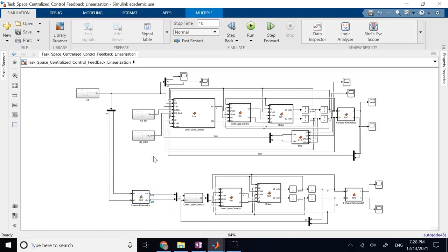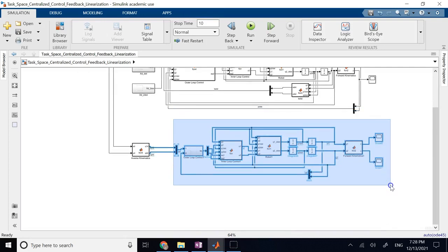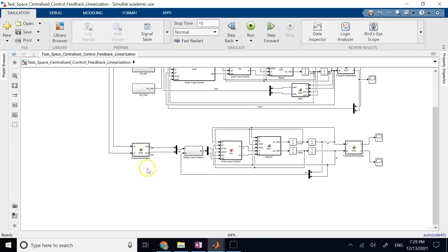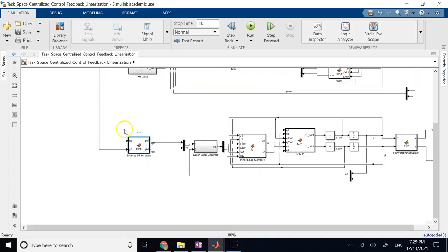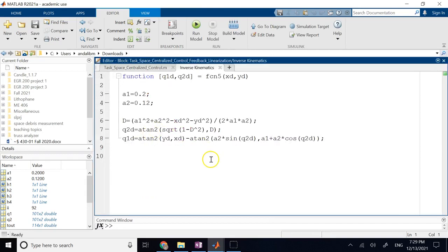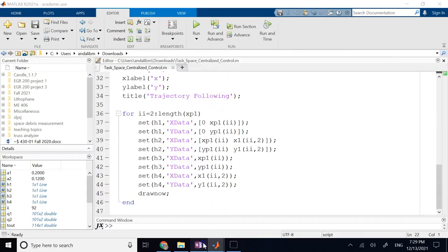Okay? As long as your inverse calculation is always possible analytically, it might not be the hardest thing in the world. But for many robots, the analytic solution does not even always exist. You can guarantee an inverse kinematic solution when your robot is not redundant and when it has a spherical wrist, if it's 6 degrees of freedom or so. So that's not always the case, that you have such analytic formulas possible,